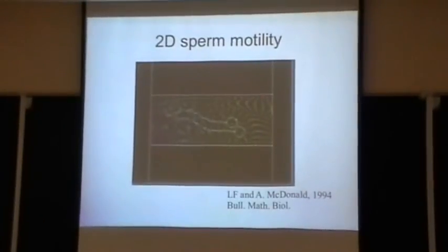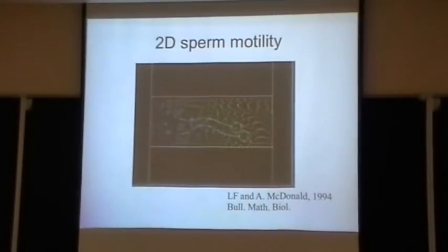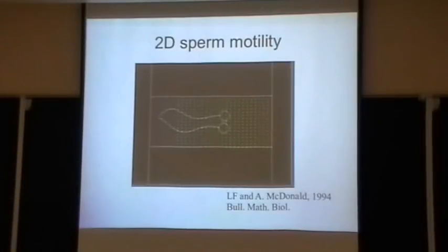They're also elastic structures. But the beauty of this immersed boundary framework is that each one of the structures is just adding to the right-hand side, to the external force. So then we can solve the fluid equations in one fell swoop without worrying about moving boundaries. It's just a force field.